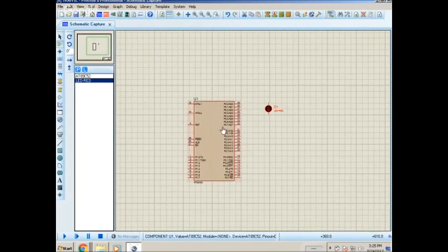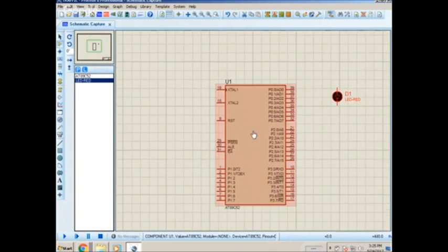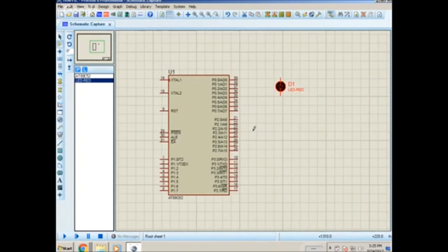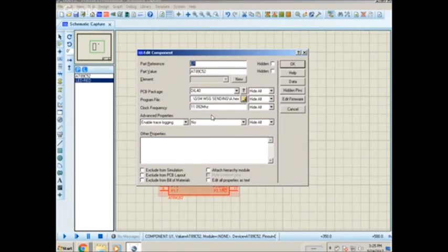In real life application, we have to install some crystal oscillators, a reset circuit, and configure some external access pins. But if you avoid these pins, it can still work. Just upload the program and run the simulation because these are the default parameters. Every IC needs ground, VCC and a basic circuit to work. So this software assumes that these are present.